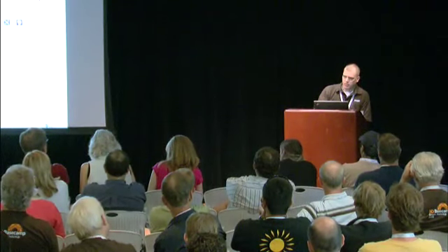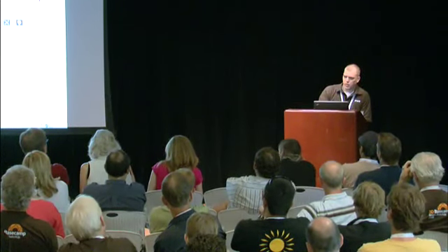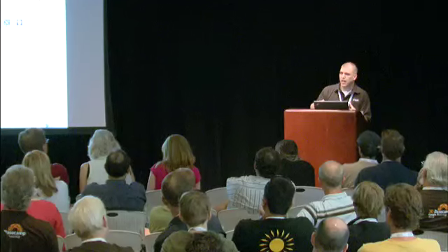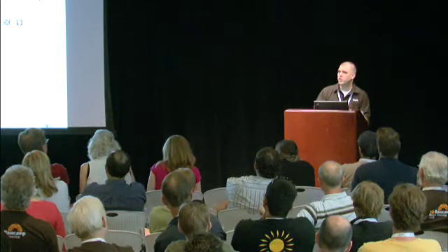We looked at this in the earlier class, a file where I had this classroom made up of various components, and as built, it had a lot of detail in it. It was around 400K file size, but once it was exploded with all the detail, it was about a 5 gig file. Okay, so exact same geometry, but if it's built out of components that are copied versus just native groups or native geometry, it's a lot bigger.